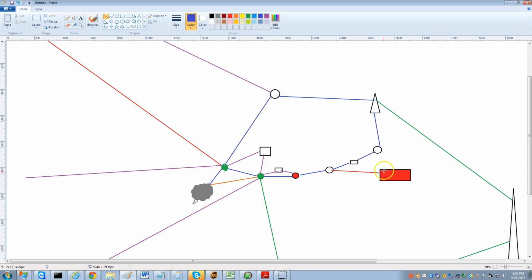Anyway, I'm in this red box here. This is a big commercial building in an industrial park that I rent for RF Armor and Netonix. There are many tenants in here. I'm in this back corner, that's why I'm called 5C. I do a bad thing and I shoot across the building. I'm about 80 feet above the roof line, which is not enough, so I have Fresnel encroachment across it. But then from here to Diller Ave, it's like 3 miles. I'm connecting into an access point like everybody else.